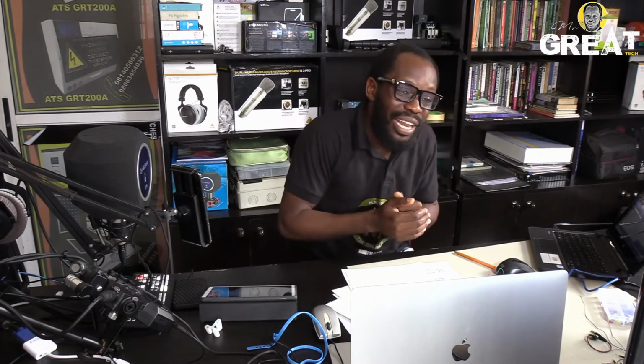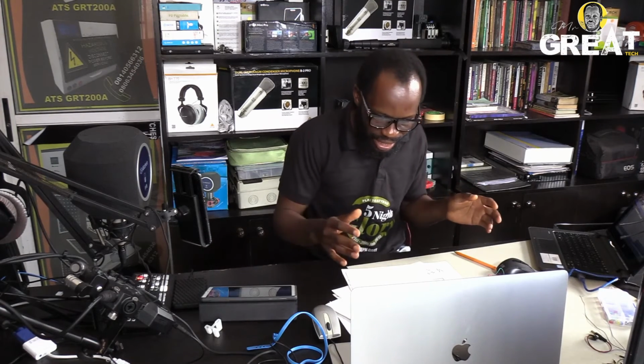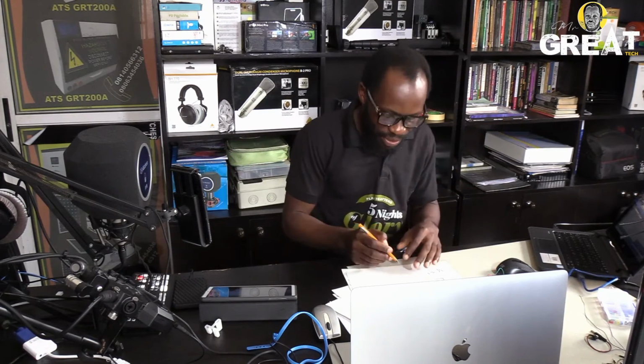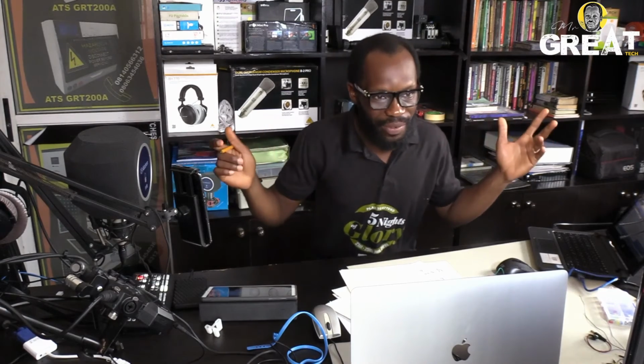Remember, in our analog read, analog write, we have a voltage scale that Arduino understands. Remember the 255. If it is 0, it is 0. If it is 5, it is 255, a scale of 255, which is 2 raised to the power of 8, 8 bits.